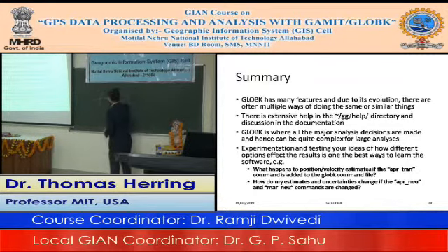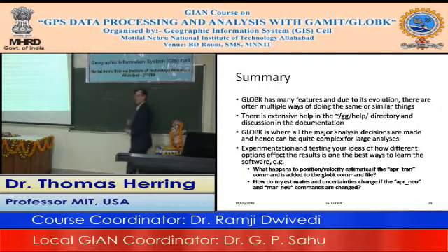And now, to link the two networks, I'm just going to form the double difference across between this pair of stations. So when you look at the way that forms the actual normal equations you form, it's not different to including this station in this network and including that station in this network.